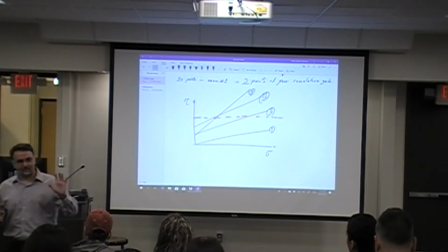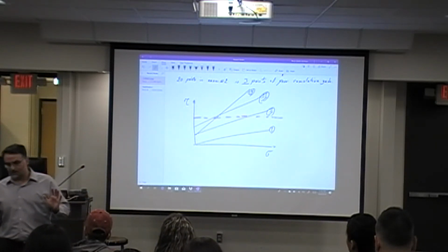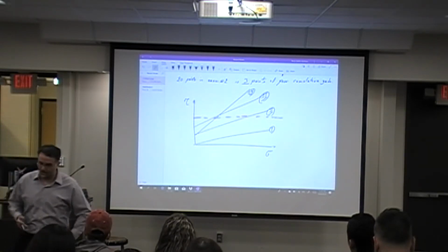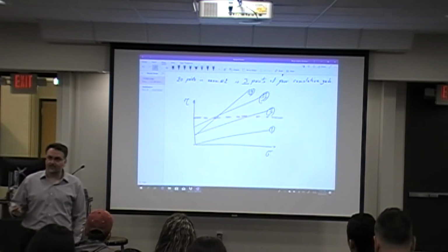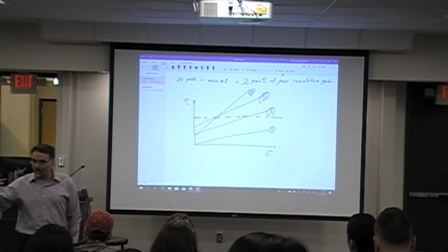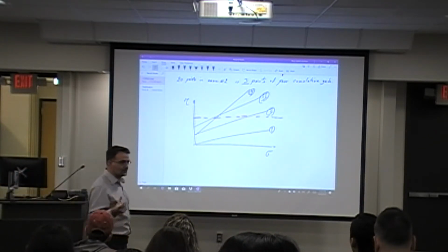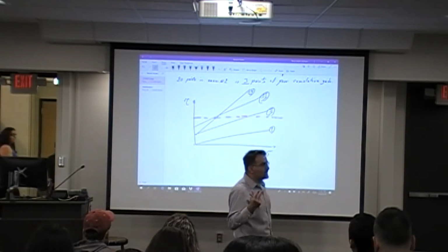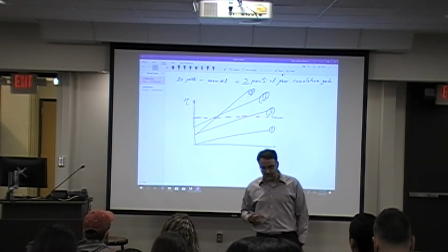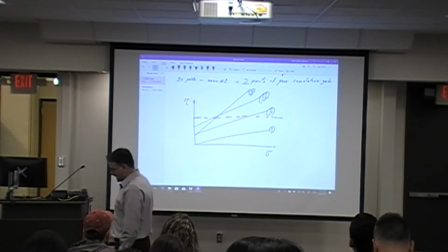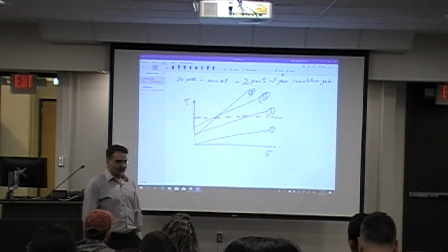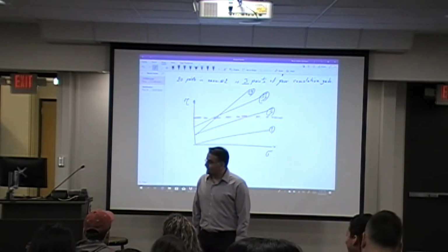Once you subtract gamma W from the saturated unit weight, you end up with gamma prime, or the buoyant unit weight. That basically comes up in the equations. The thing that you have to show essentially there is the change in the slopes, right? Remember, from one medium to the other, the slope of the lines is going to change, because the slope of the distributions are the unit weights, right? The unit weight in each layer is the slope of the line. So that's basically what you had in your exam there. And you notice you do not even need to use your equation sheets. Right? So that's what we had for the first exam.